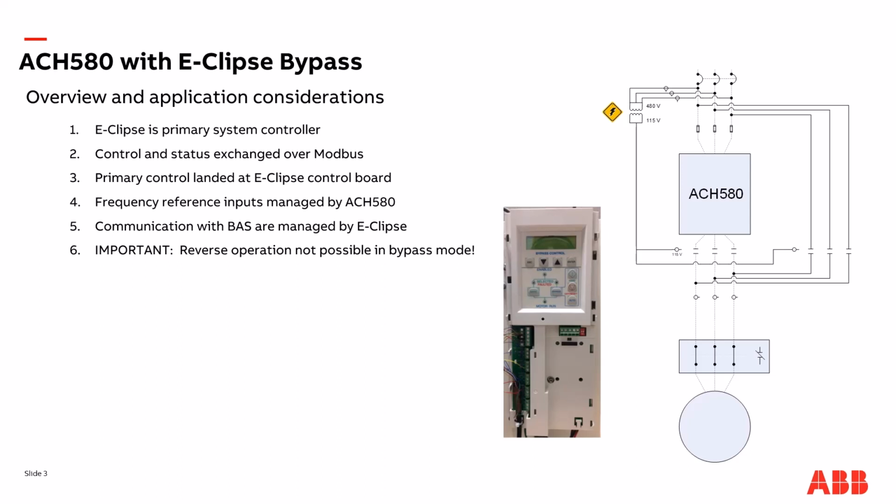And finally, the most important takeaway of this introduction is to point out that reverse operation for de-ice control is not possible in bypass mode. This is only possible when the ACH580 is controlling the motor. And with that, let's get into the rest of the material.